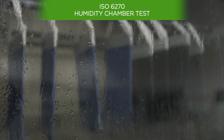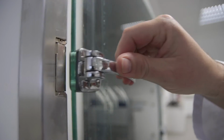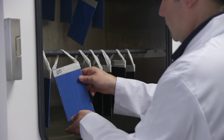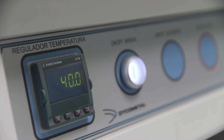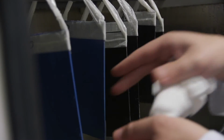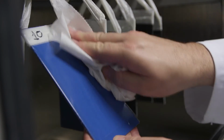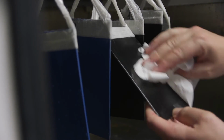ISO 6270, humidity chamber test. The test consists of assessing resistance under high humidity conditions. It consists of a temperature controlled enclosure with a distilled water tank that is electrically heated to saturation. The paint testing cards are assessed every few hours according to ISO 4628. Failures can be blistering, decoloration, chalking, etc.